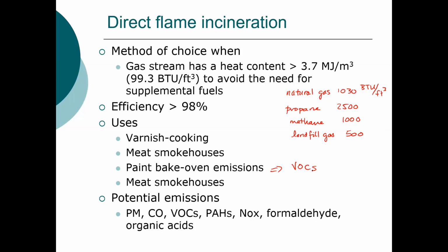On the other hand, you will not have complete combustion, so we produce particulate matter, carbon monoxide, various different VOCs, various different polycyclic aromatic hydrocarbons, NOx, formaldehyde, organic acids, and also SO2. You can also produce chlorine and fluorine, depending on the sources.